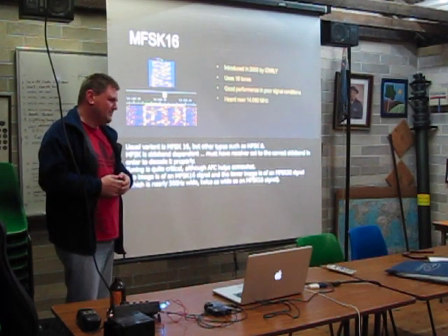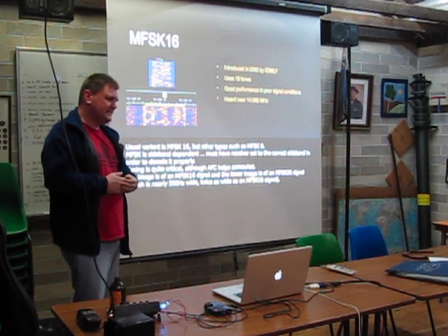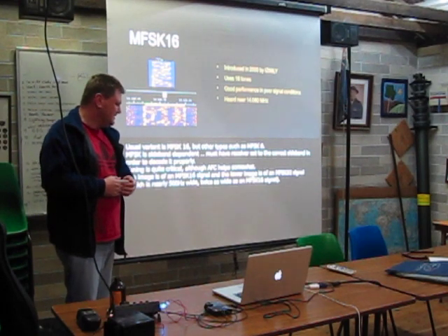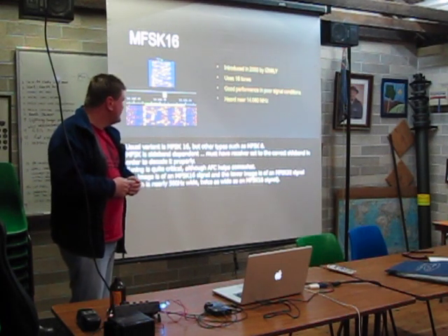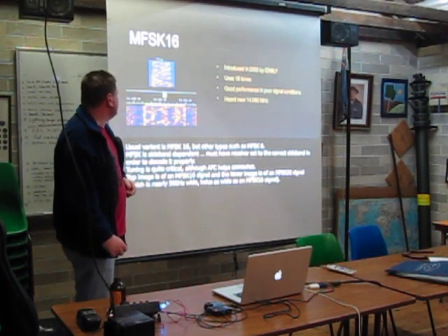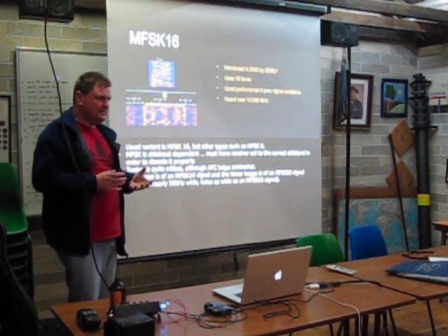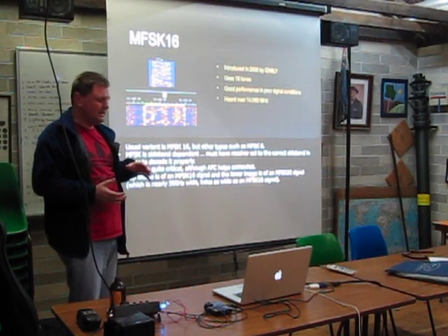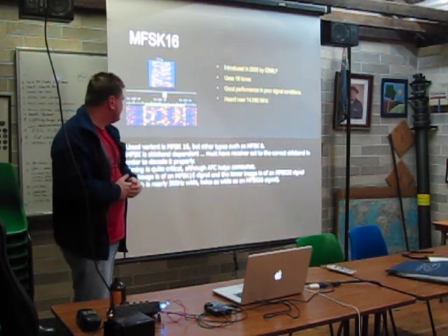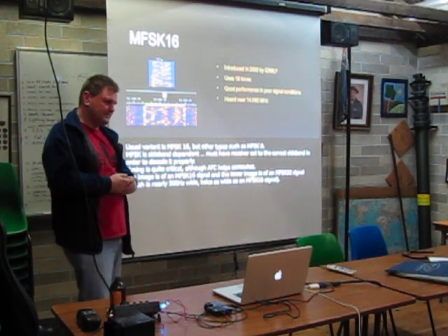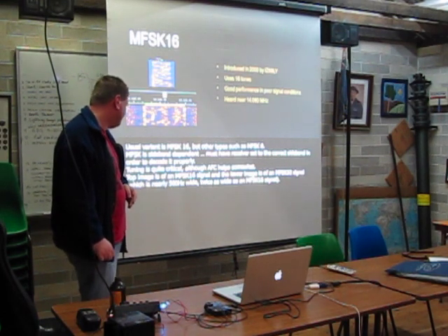So it means you can get by with a Class C amplifier, for example, or even Class D mode that I think they're using on the new 630 metre band. It's quite common to use a Class D amplifier. So there's some good advantages for this frequency shift keying method. With phase shift keying, the linearity becomes extremely important, and the power output also varies a lot, the peaks and troughs. So linearity in a phase shift keying system is quite important. It's less important in frequency shift keying.